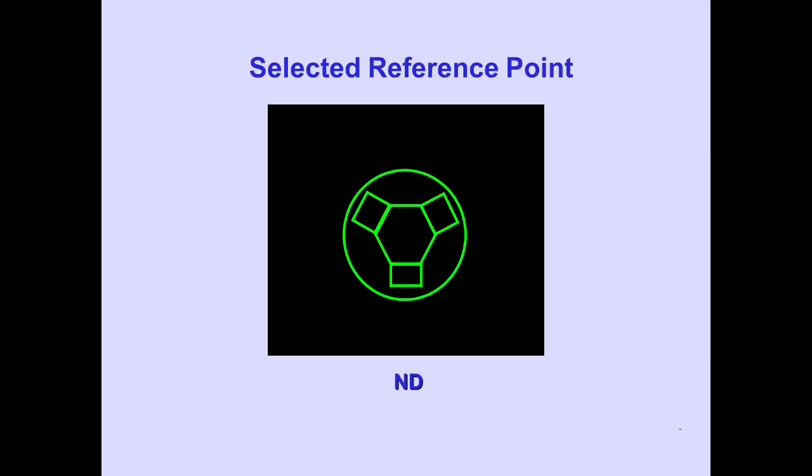A point selected on the FMS CDU fix page is identified by a green circle around the selected reference point. Airports, waypoints, or Navaids can be used. This is covered in standby navigation.